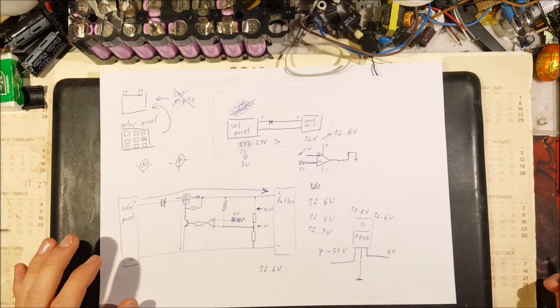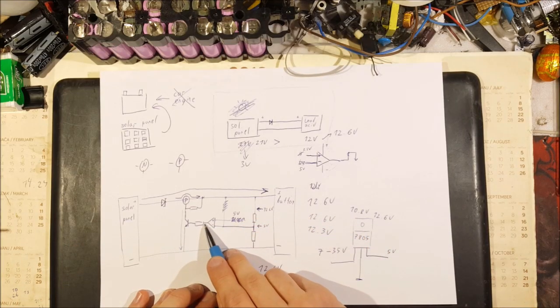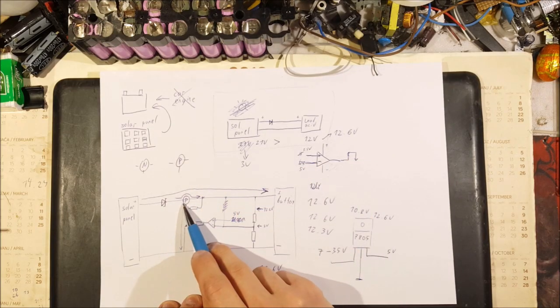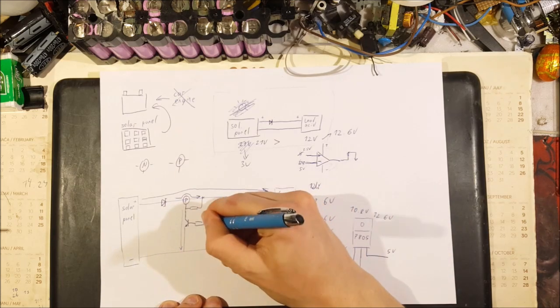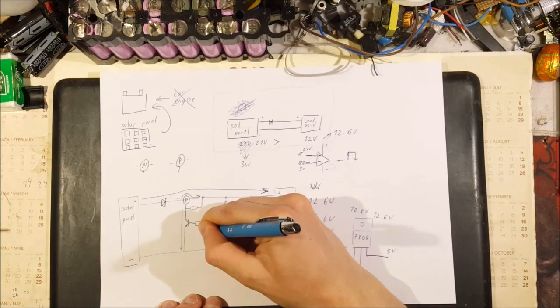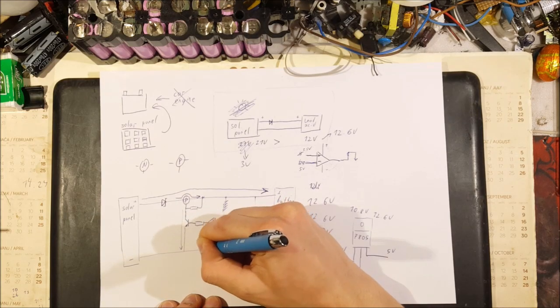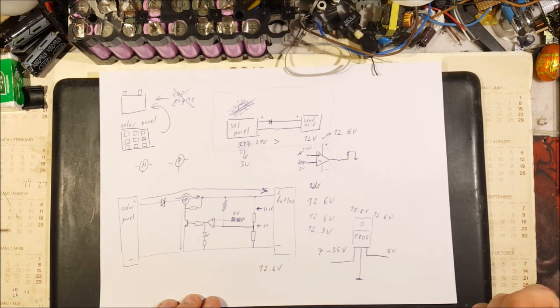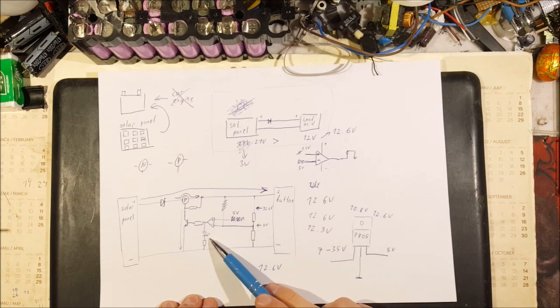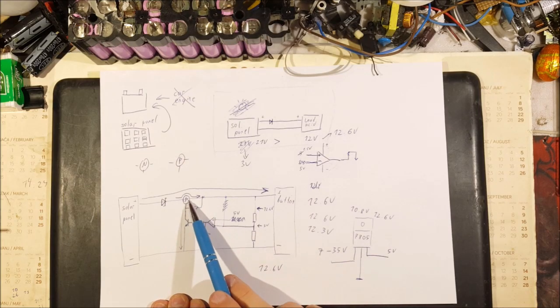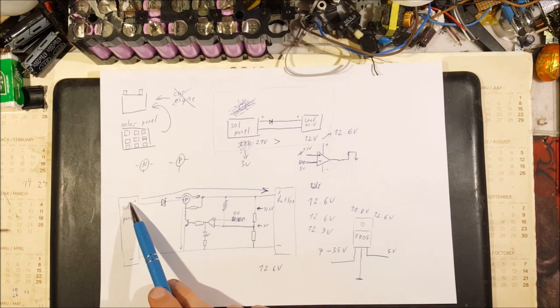Now a logical thing would be, because this output right here is high when this MOSFET is turned on, meaning that if we simply add a diode right here, with a simple resistor to ground, we will indicate with this diode every time that this MOSFET is turned on, thus indicating every time when it is letting the power flow from the solar panel to the battery.